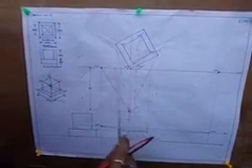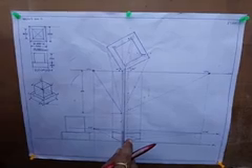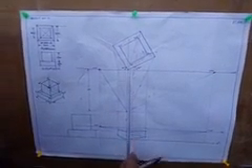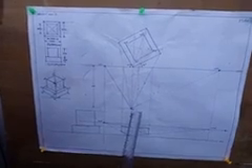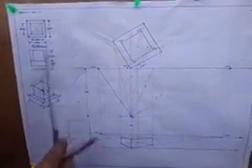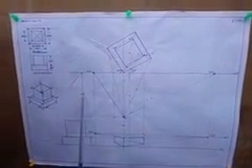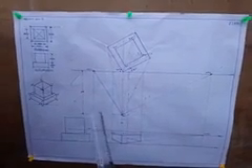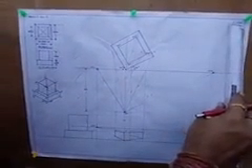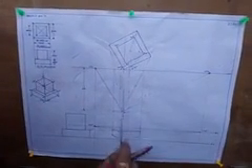Then from this point, which is kept over the picture plane, draw the vertical line down to the bottom, and on this line mark the station point at a height of 2h. Here the total height is 3 meter. So 2 into h, that is 2 into 3 meter, is 6 meter. All this perspective we are drawing in a scale of 1:50. So 6 meter converted in 1:50 is 12 centimeter.